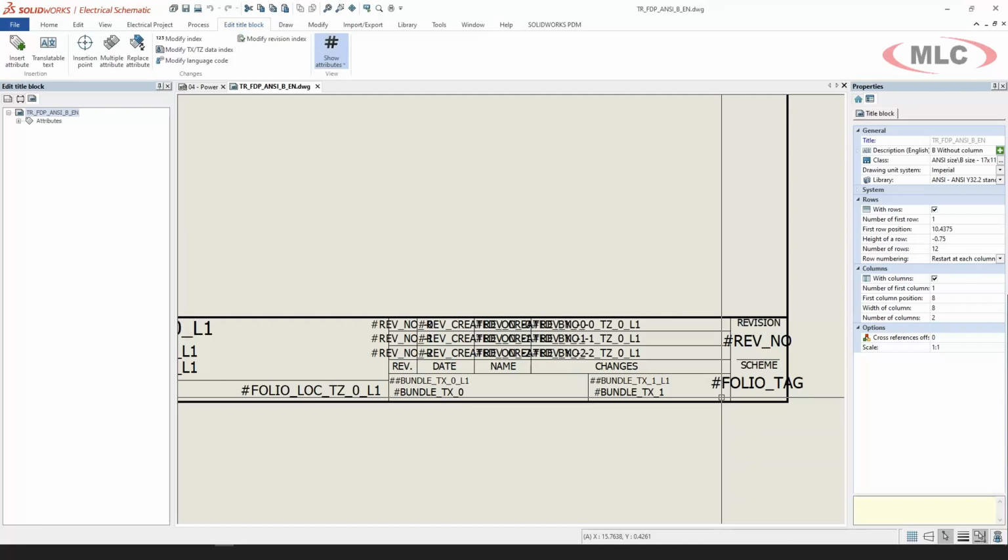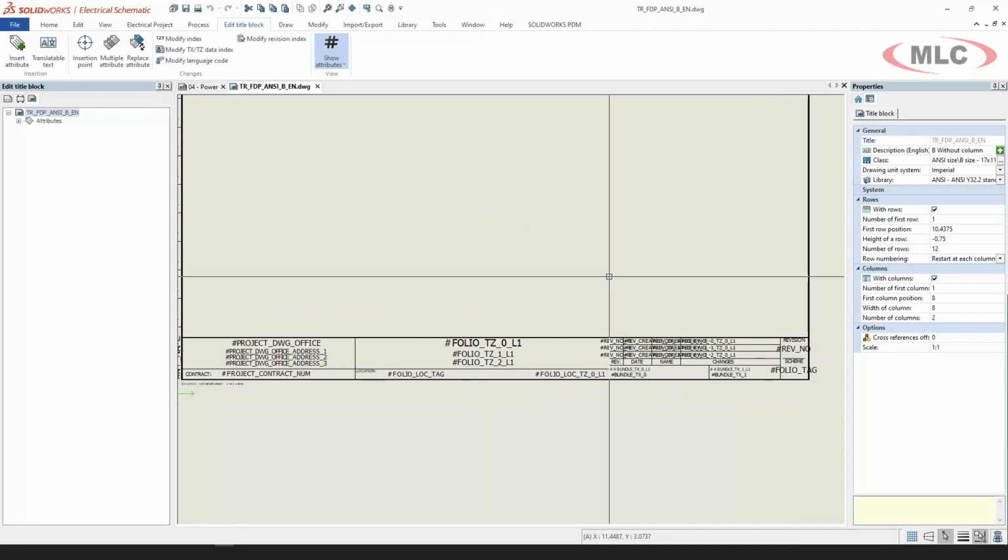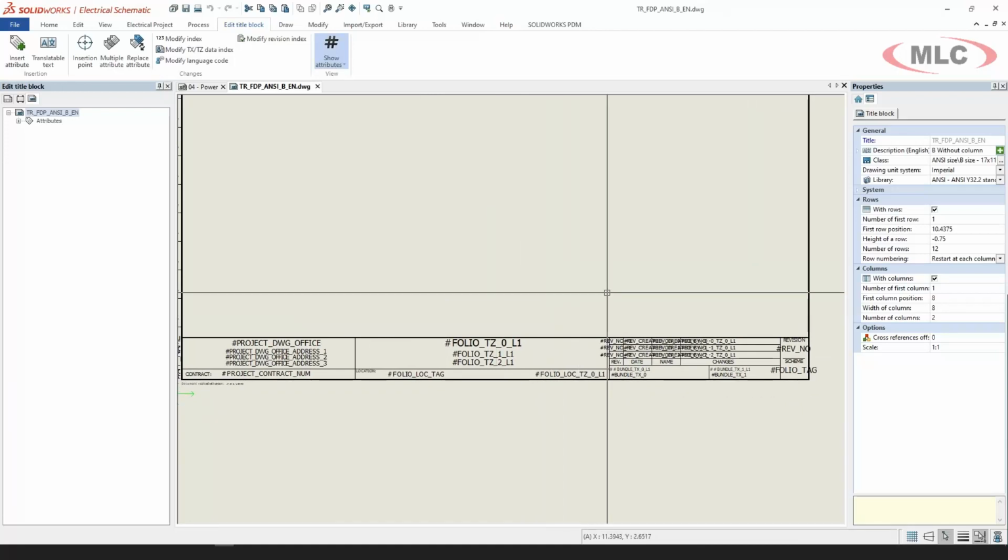That means if your title blocks are set up properly, and we help you set those title blocks up with electrical services, you could go to the project information and make a change, and every single page reflects that. If you're creating notes for revisions on every single page, and you have to do that whenever you bump a rev, just think about all that work going away. You just don't have to do it anymore. But adding images or customizing the way this block looks down at the bottom, sometimes they want them up on the top or the side or in one corner, depending on your company standard, we can make this title block sing.